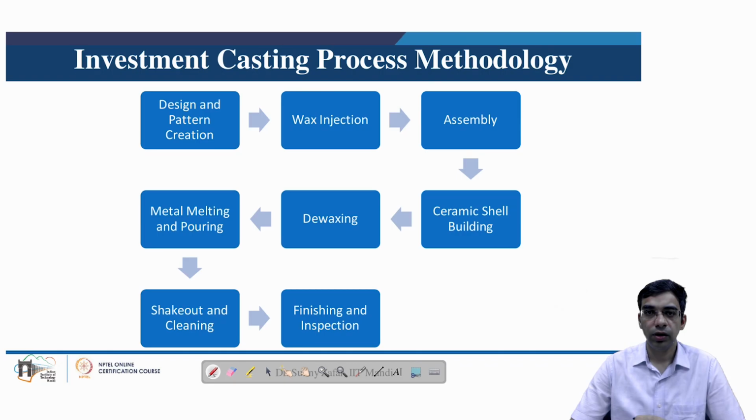So this is the overall methodology of the investment casting process, which starts with design and pattern creation. Then is the wax injection process. Then is the assembly. Then is the ceramic shell building, dewaxing, metal melting and pouring, shakeout and cleaning, and lastly is the finishing and inspection.